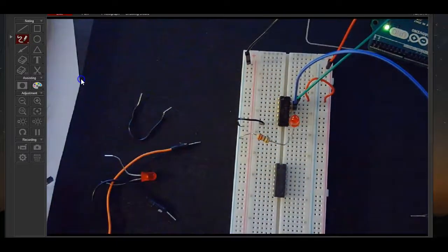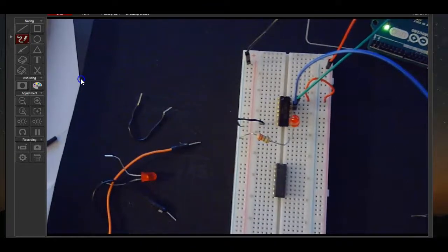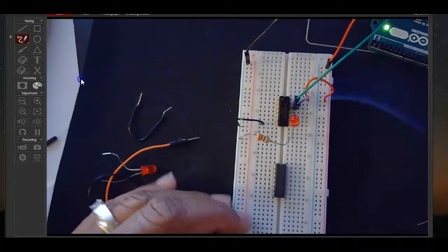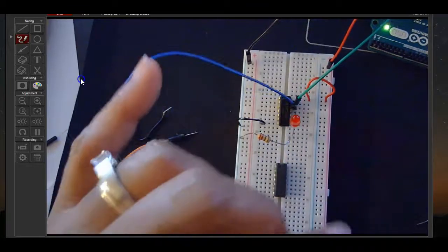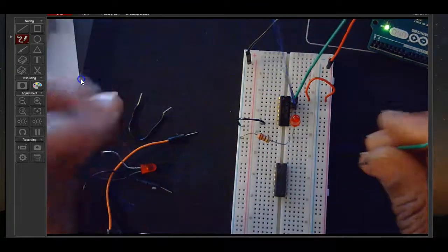So how does a NAND work? The way a NAND works is that if any of your inputs are 0, you get out a 1. The only way you get out a 0 is if you have 2 high inputs, or 2 ones. So let's start with 0, 0 as our input.